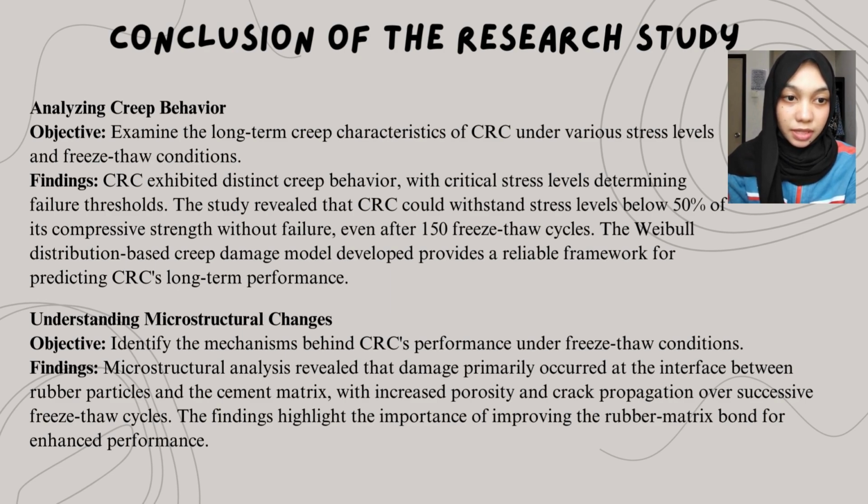The study revealed that CRC could withstand stress levels below 15% of its compressive strength without failure, even after 115 freeze-thaw cycles. The Weibull distribution-based creep damage model developed provides a reliable framework for predicting CRC's long-term performance.